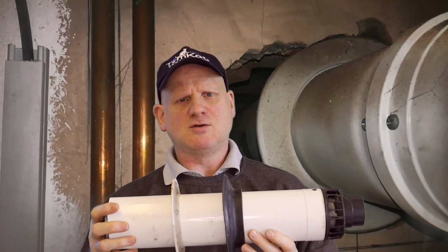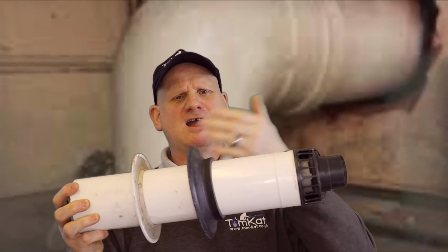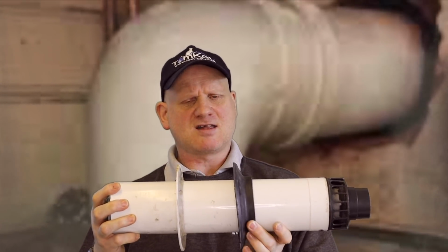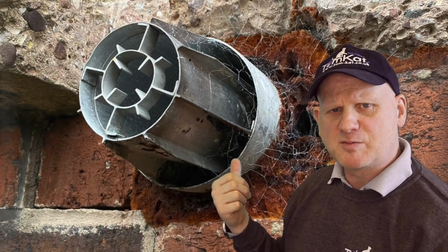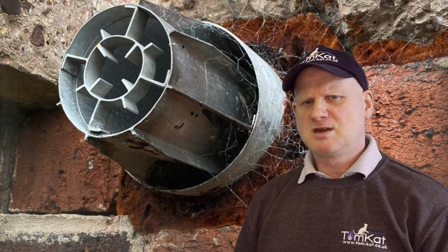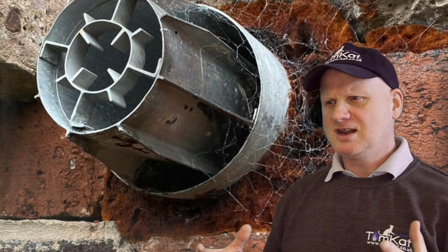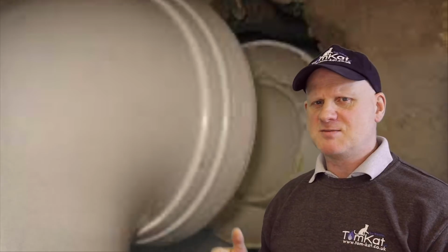So what they're saying to do is, even though the manufacturer says this will stop products of combustion and rain entering the cavity, GasSafe are still saying you should sand and cement the flue inside and outside. Also, things like expanding foam aren't allowed because they're not weatherproof. Some silicones are not allowed either because they shrink. So you have to check the manufacturer's instructions to see what materials you can use for sealing the wall. Sand and cement is perfect.